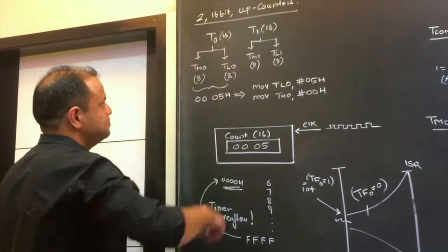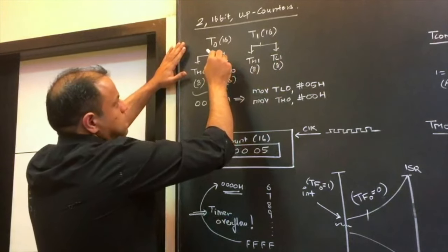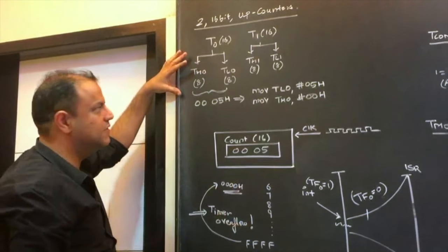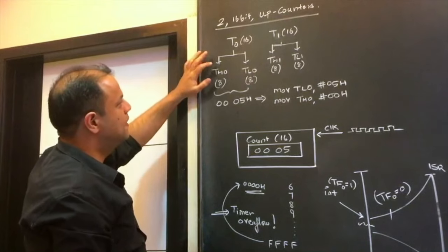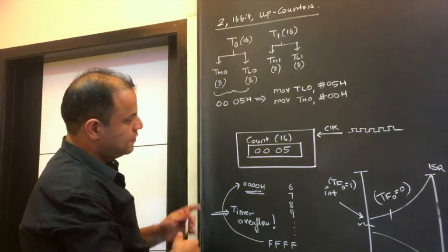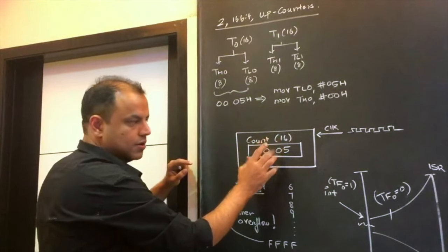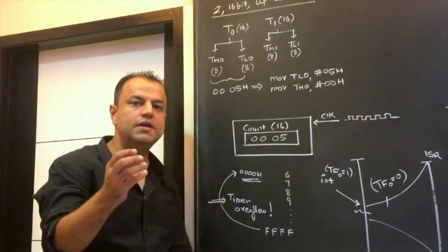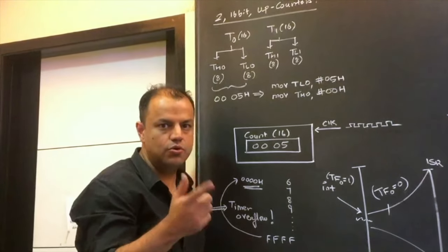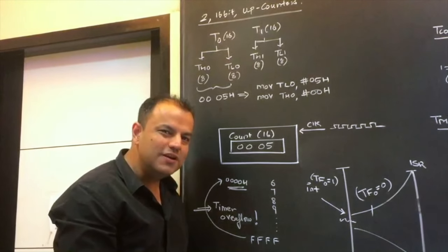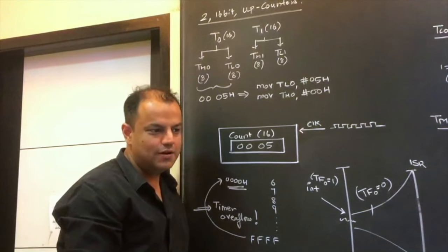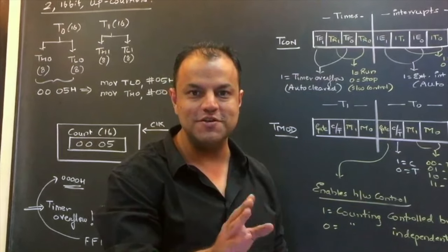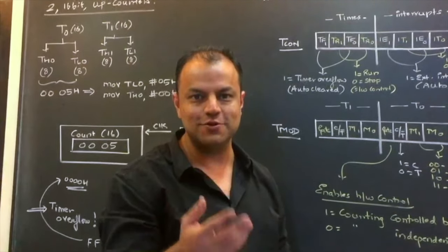So these are your two timers. They are identical. You can study any one timer, the other does the same thing. So let's look at timer 0. The first thing, as I said, is we have to load a count. The count will be a 16-bit number. To hold the count, we need a register, which will be an SFR. I'm sure you know what an SFR is. SFR stands for Special Function Register. So you need some special register to hold this count.